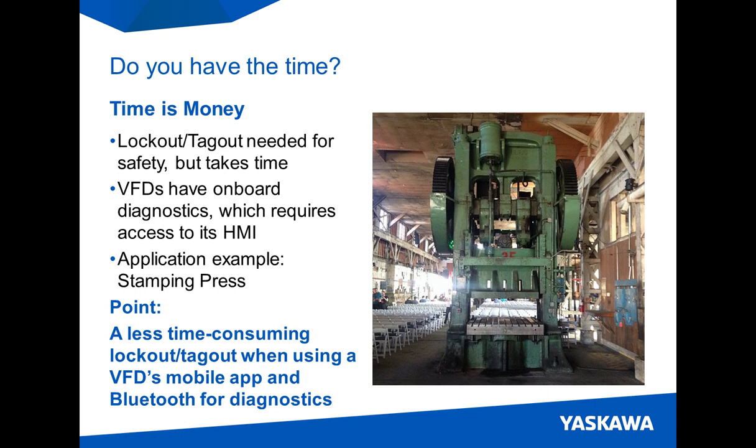So one example I provided here is a stamping press where maintenance personnel could check drive diagnostics with a wireless Bluetooth connection from 30 feet away. That can save time and productivity by avoiding the need to interfere with equipment operations. This can also be the situation for facilities with very few standalone VFD applications or installations.